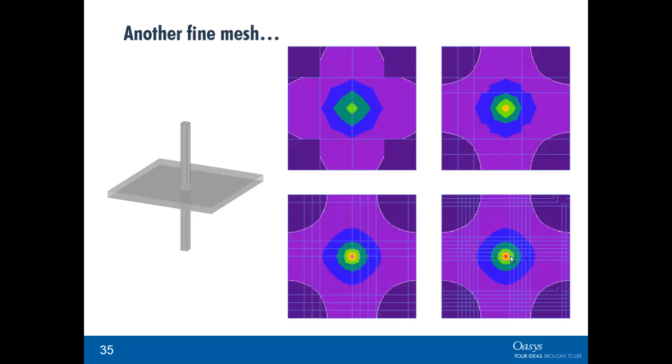So whether you just say, here the mesh is fine enough. I mean, this mesh in the bottom left is probably sufficiently fine. The contours are pretty smooth, not perfectly, and likewise the peak moments within the column area I can probably ignore. So it's worthwhile increasing the mesh density, but remember that in certain circumstances it can lead to strange results.